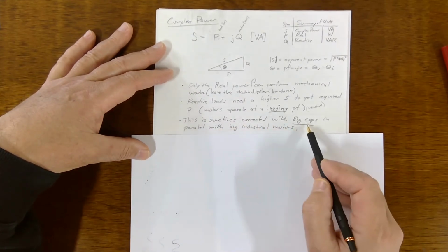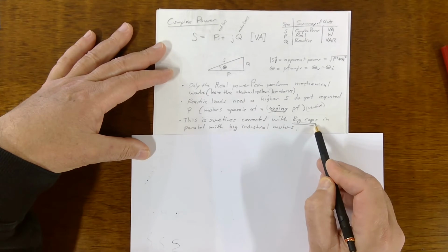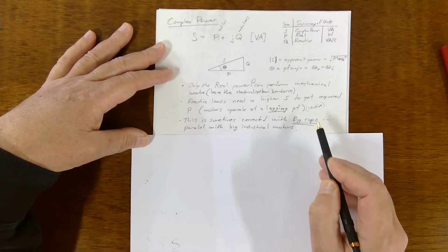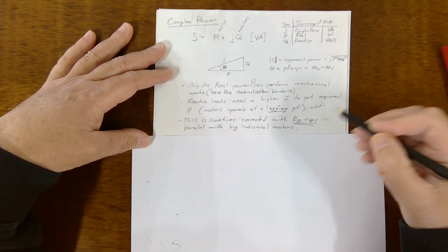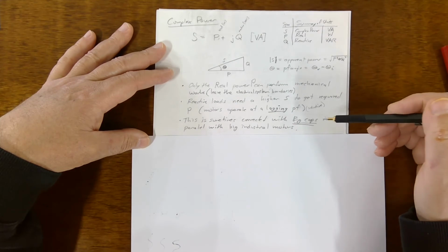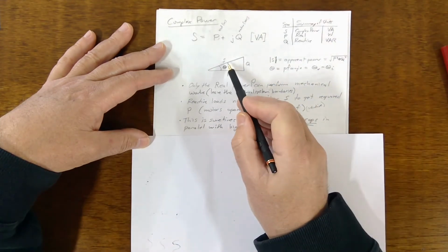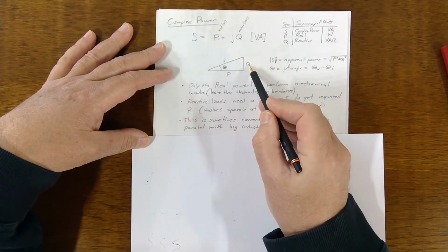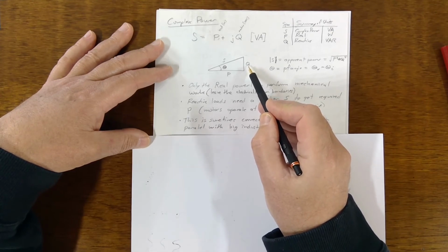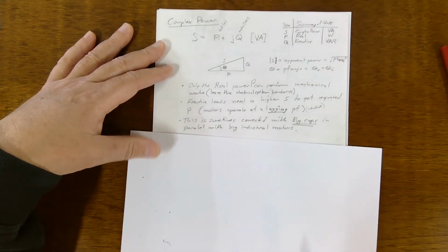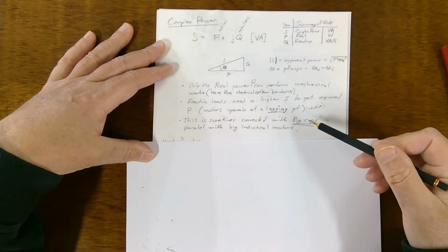So sometimes in industry they'll use big capacitors to balance out the inductance, and we'll work a problem like that, where there's an inductive circuit and you're trying to balance out the power so that the apparent power S doesn't get too big. You're trying to balance the reactive part of the load. Ideally, you want to cancel it out if you're trying to maximize power, but we'll talk about that. Anyway, that's the phasor view of that.